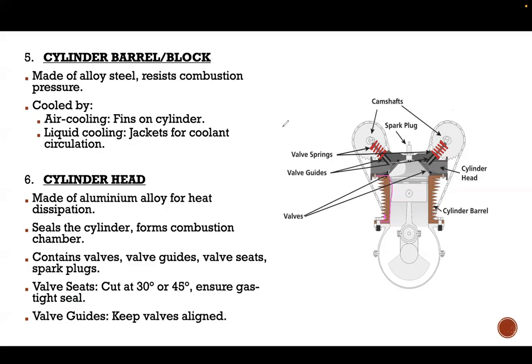your engines. Whenever we use an air-cooled engine or a liquid-cooled engine, we'll talk about air-cooled engines first. In case we use an air-cooled engine, the whole side of your barrel, let's say this is your cylinder, will have a few metal pieces popping out of your engine. These metal pieces are called fins. You can easily see this on any bike. If it stands, you can see small pieces protruding out of your engine.